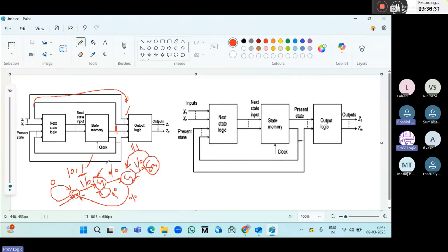Okay. And Ma'am, I have one doubt. From S2, why is it going to S0 and not to S1? Even if it goes to S1, it can form a sequence, right? 1011. But why does it have to go to S0? Here these sequences we can write anyway, as long as we get the proper flow 1011. Here I'm just showing how we can write the states.